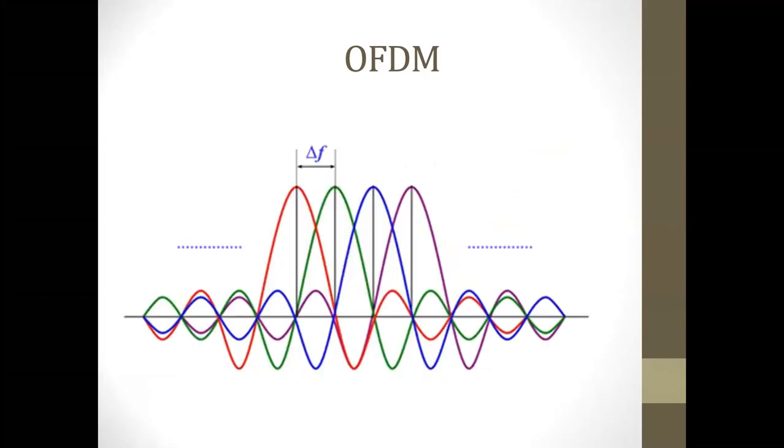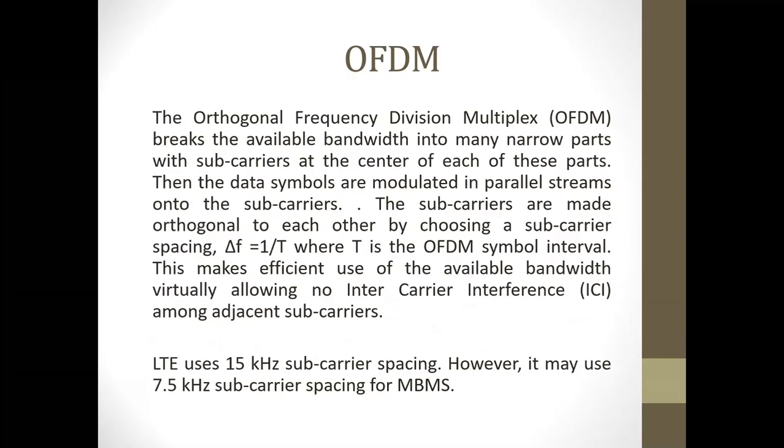And then to make sure that you don't have inter-carrier interference, or to avoid ICI, you need to allow a good amount of margin between the carriers. And that will cause too much wastage. That wastage will overpower all other advantages. I mean, that wastage will outweigh what you get out of the flat fading.